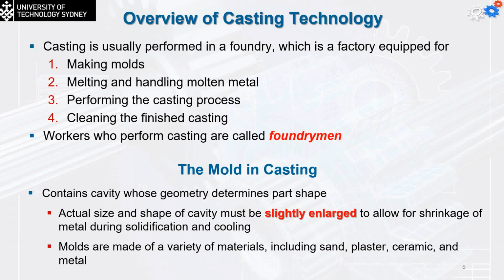The expendable one can give you more complex geometries than the metal one. I can make complicated cavities with sand casting because inside I have sand. I can simply clean it out and get the geometry required from the inside details. But for metal, it's usually going to be a simple shape so I can open the die parts.